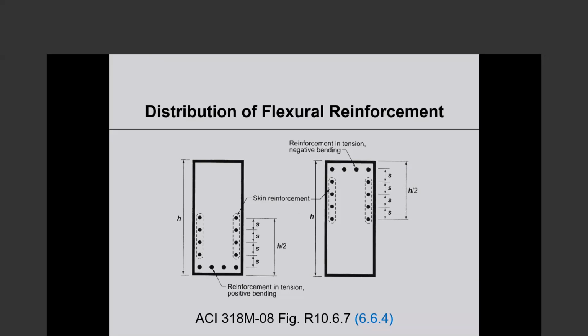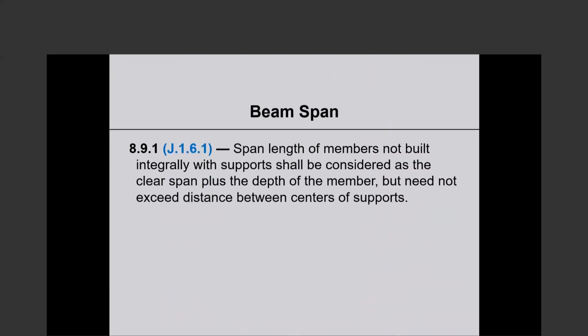Okay, once we got into design, we talked about maximum reinforcement ratio, minimum reinforcement ratio, the crack control through imposing maximum spacing on the extreme tension reinforcement, and now skin reinforcement, which is for deep beams only, depth exceeding 900 millimeters.